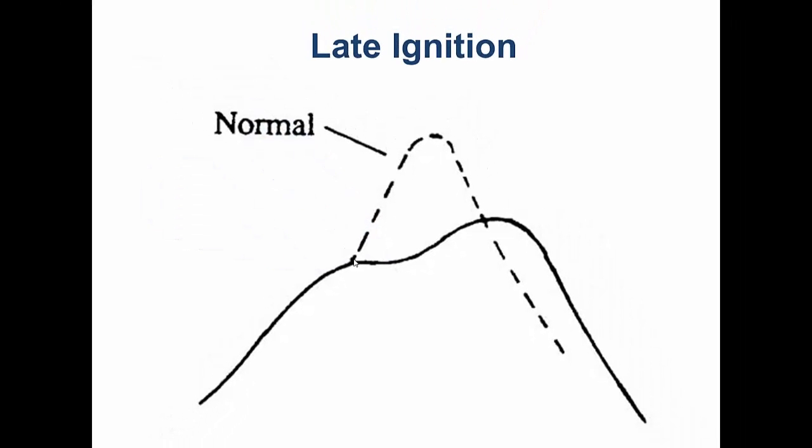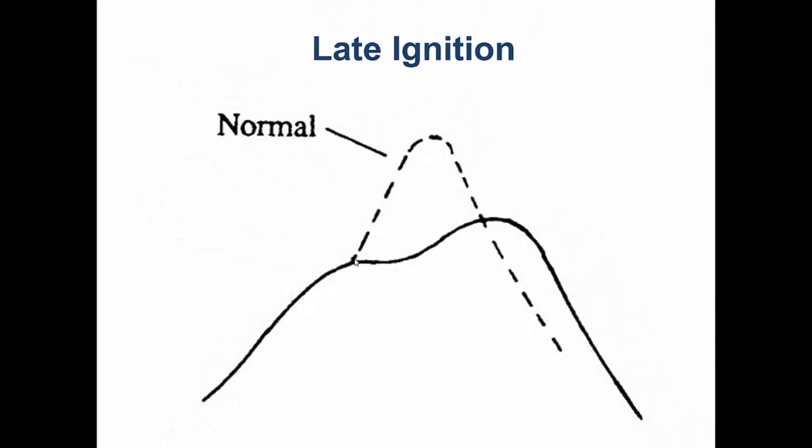When that occurs, that piston is accelerating downwards, and the volume is changing rapidly and increasing rapidly. So when you inject it late, the volume is quite large, and you will get a significant drop in the Pmax pressures. And ignition occurs down here instead of where it was supposed to, which is right over here.